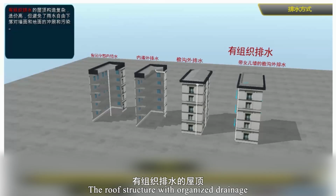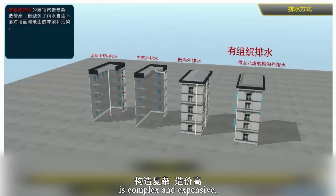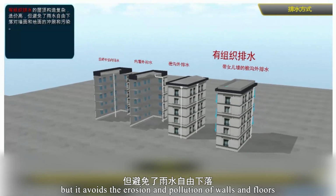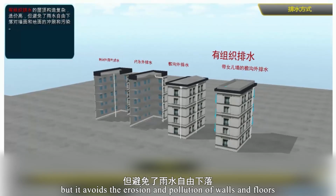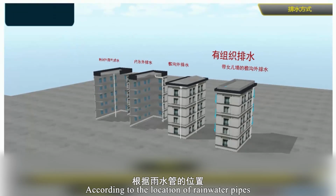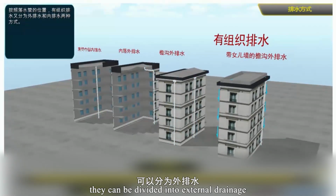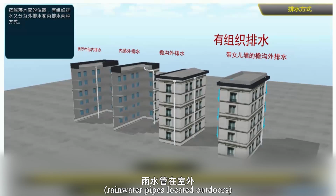The roof structure with organized drainage is complex and expensive, but it avoids the erosion and pollution of walls and floors caused by rainwater falling freely. According to the location of rainwater pipes, they can be divided into external drainage, with rainwater pipes located outdoors, and internal drainage, with rainwater pipes located indoors.